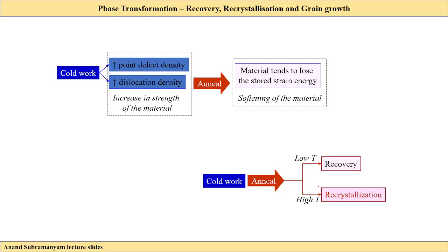Now, if I have a small grain size, that means there is more grain boundary, higher dislocation pile up, and higher backstress being applied. That's why people stop at the fine structure. They do not give enough time to have a coarse structure. That is the famous Hall-Petch relation, where the yield strength will increase with decreasing grain size. So that is about recovery, recrystallization, grain growth.